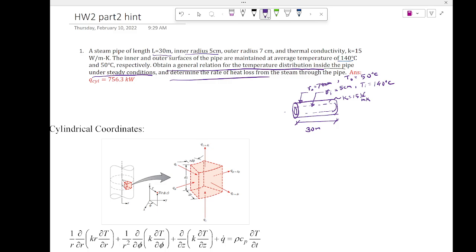You just say applying boundary condition at r equal to ri, T1, at r equal to r0, T2, and then remember the equation that I wrote, T equal to what? Like C1 ln r plus C2, and write that from the equation manual. And then next line, C1 equal to, remember I have the C1 value. After applying the boundary condition, you're going to get that C1 and C2, right? So write those, and finally write the T equation. This is all in the equation manual and in books. The reason it is given here, instead of you only applying the equation, is so you know what is going on in the background. Does it make sense?